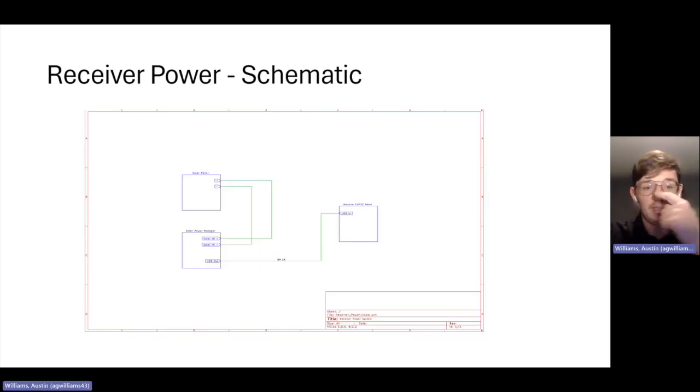And moving on to the schematic here, this is a very bare bones schematic showing that we'll be using solar energy to charge the lithium ion battery in the module there. And then from that module, we'll be using USB-C connection to power the ESP32. And any additional modules can be powered from the Nano itself.